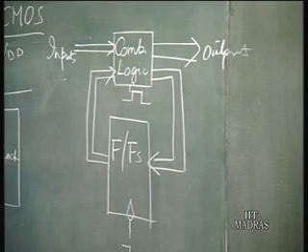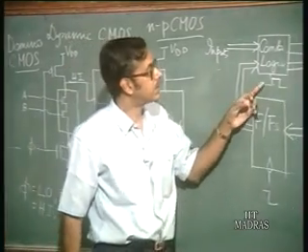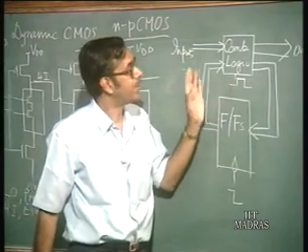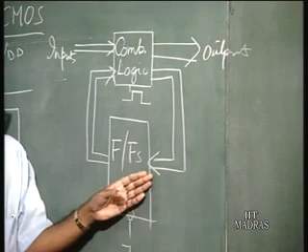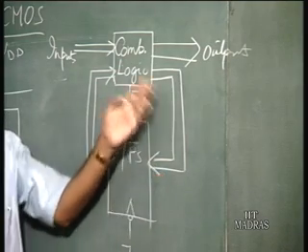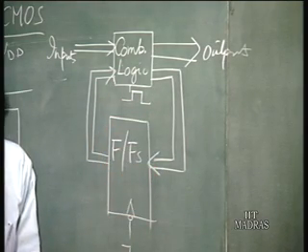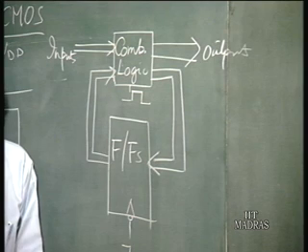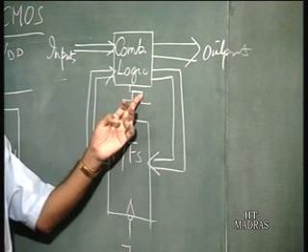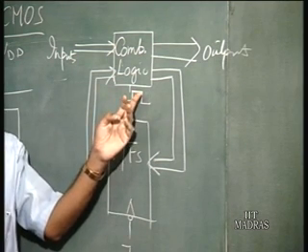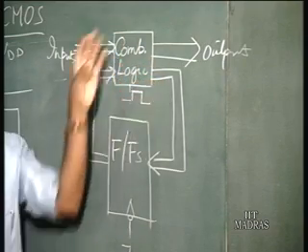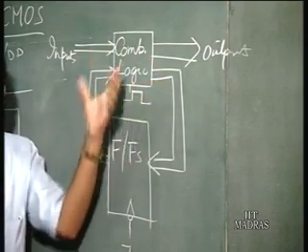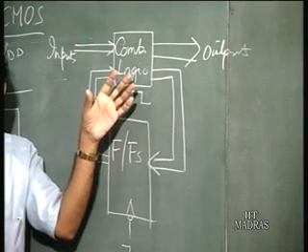So what happens is the similar circuit as we have already seen. When the clock is low, it is in the pre-charge phase. The output here comes here, but it is not going to affect the flip flops because the clock is low. Now, when the clock goes high, you have the evaluate phase. During this time the output of this combinational logic block is going to change depending on the inputs to that combinational block.